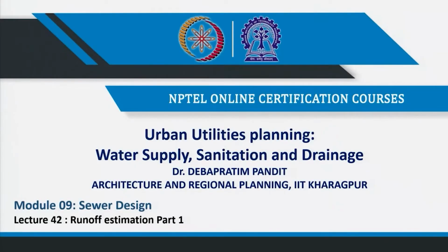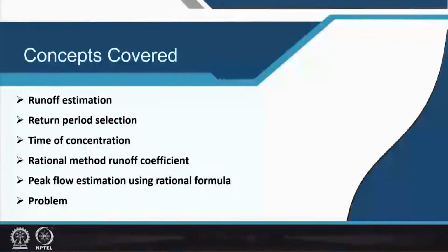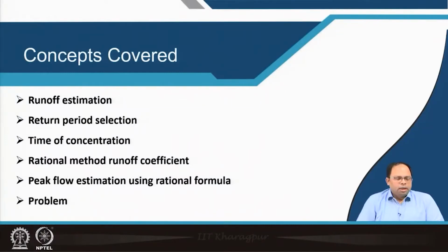Welcome back. In lecture 42, we will cover runoff estimation. This is the first part. The different concepts that we will cover will be the requirement for runoff estimation, return period selection, time of concentration, rational method runoff coefficient determination, and peak flow estimation using the rational formula, and finally, we will solve a problem.